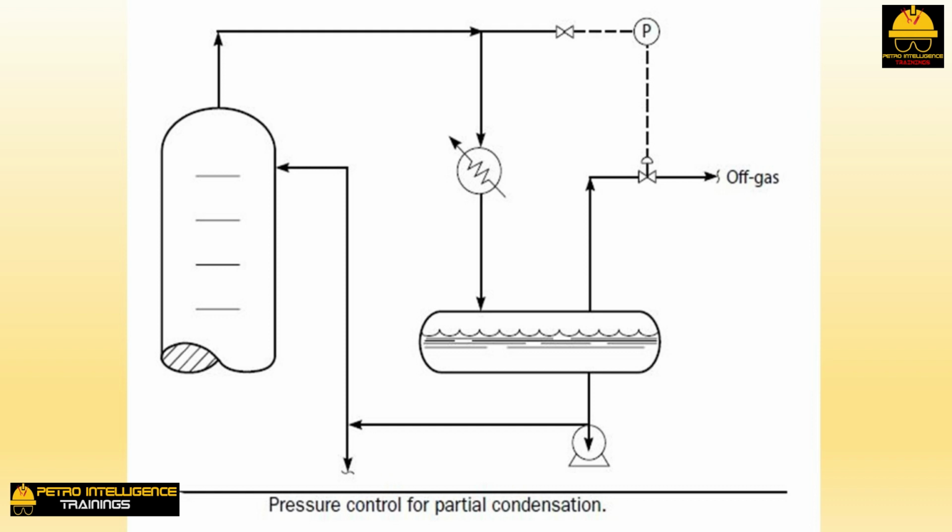Sometimes we see tower pressure control based on feeding a small amount of inert or natural gas into the reflux drum. This is bad. The natural gas dissolves in the overhead liquid product and typically flashes out of the product storage tanks. The correct way to control tower pressure in the absence of non-condensable vapors is to employ flooded condenser pressure control. If, for some external reason, a variable level in the reflux drum is required, then the correct design for tower pressure control is a hot vapor bypass.